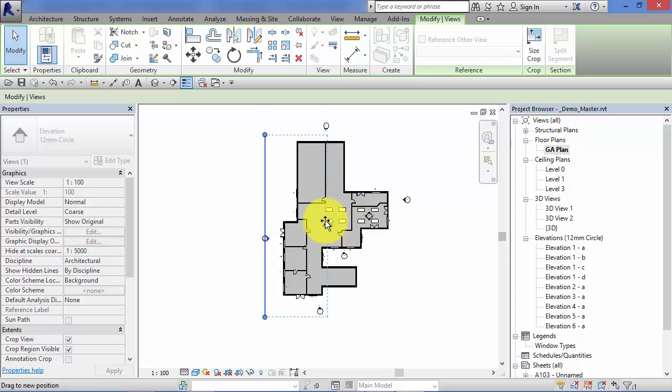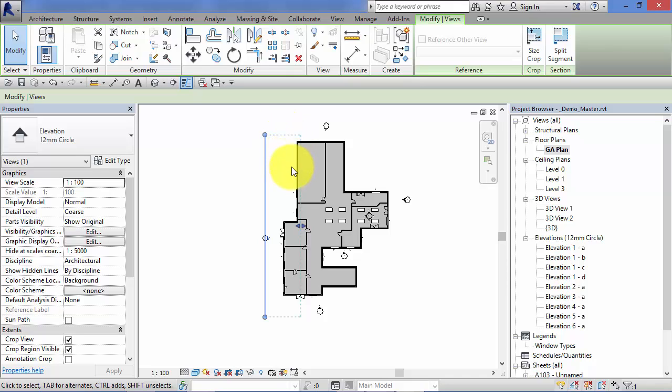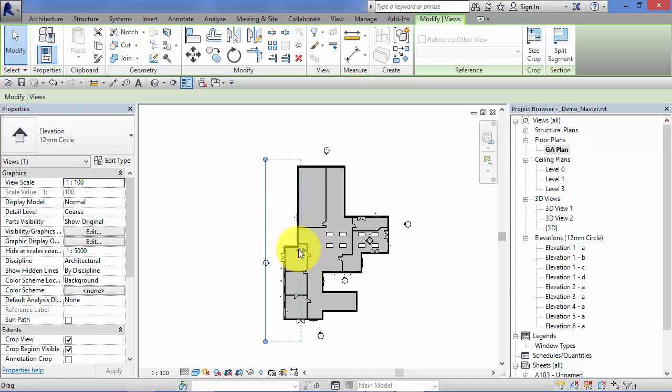So generally with elevations, you're going to set it just behind the line that you would actually be able to see in real life. So no matter how much further we pull it across to the right, we're not going to see any more in the elevation because it's masked by these walls. So it's more efficient to just keep that pulled back just to the depth you need.